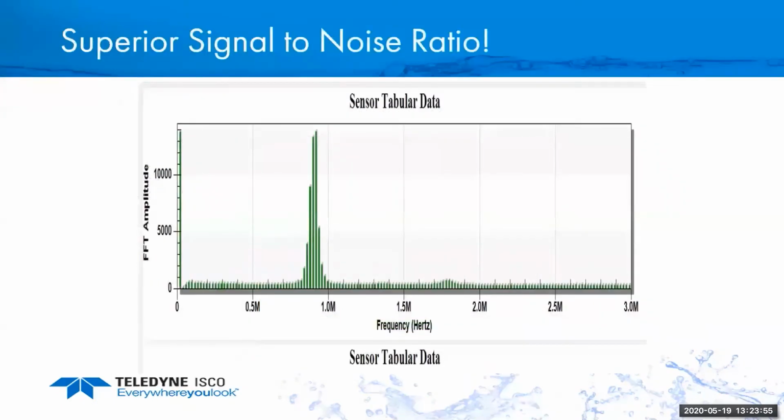So let's zoom in a little bit more. Here's another site. This is what it's all about, the signal versus the noise. So this is signal to noise ratio. The noise floor is on the bottom. We want very low noise. We made a lot of improvements on the laser technology so that we eliminate that noise floor, minimize that noise floor. What that really means is that the laser can read extremely slow velocity.